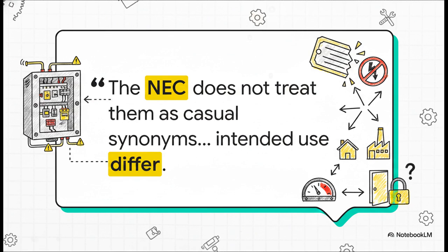A bad label isn't just an innocent typo, it can literally ruin your service entrance specs. Worse, it creates incredibly dangerous assumptions about access. Just imagine an electrician walking up expecting a front access-only panelboard, but instead they're face-to-face with a switchboard that has exposed energized rear buses requiring totally different clearance rules. Yeah, that's a massive safety hazard.